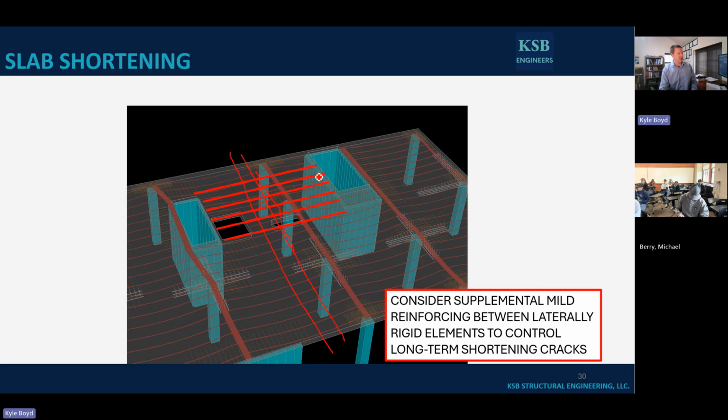So what am I going to do? I'm going to put a couple horizontal pieces of rebar in there. I'm not going to do any math behind it. I've already said I'm going to lock this thing off after I know the shrinkage is less than 1/4 of an inch per 100 feet. So I've already figured out that math. I detailed it properly by putting in this pour strip, or maybe I did that slip connection that I was showing you on the top of the walls with that angle, remember, we'll go back.